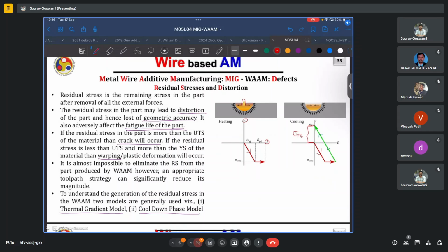Whereas if by some process such as in situ hammering, in situ shot peening or laser peening, we were able to induce residual compressive stresses into our part, then had a crack formed inside the part, the residual compressive stresses would have tried to close that crack or would have inhibited its further growth.